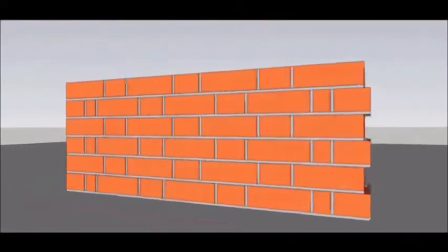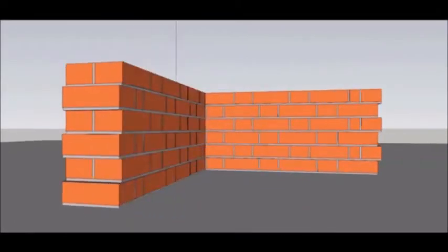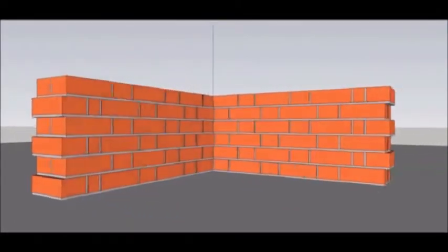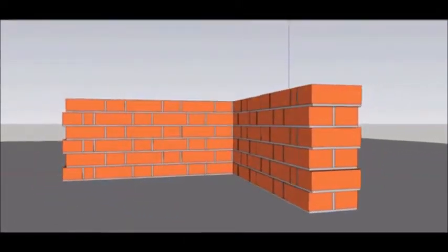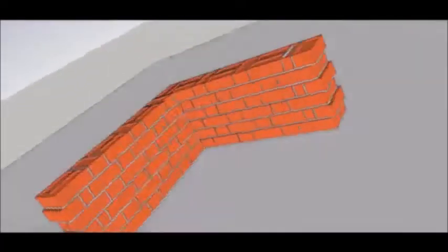One brick thick walls are easier to produce a fair face on both sides in Flemish than in English bond, and that, in the opinion of many, the appearance of Flemish bond is preferable to that of English bond.